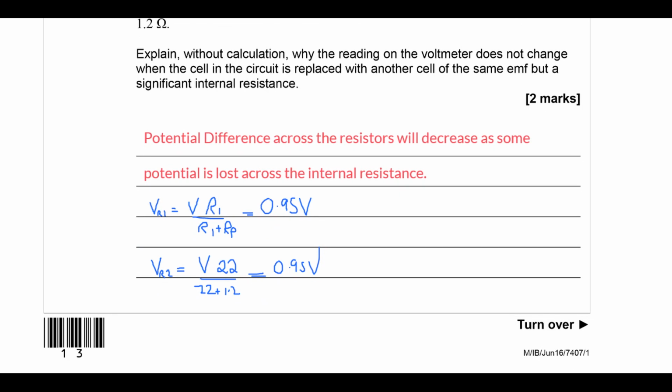So around each loop, they have the same potential difference across the whole section, and they lose the same amount of potential across the first resistor in the section. So essentially, A and B are at the same potential, therefore they have a potential difference of 0 between the two, as long as our voltmeter has infinite resistance, so it doesn't affect our circuit.